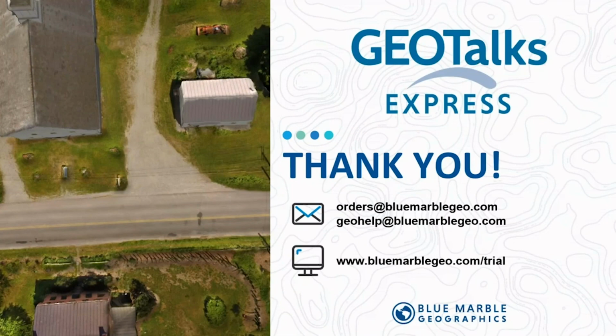Somebody asked very quickly, how do they generate the flight line? It happens automatically. Again, load your drone images into the Pixels to Points tool. I believe it's an option in one of the menus at the top. Mackenzie, I don't know if you can remember. It's from the map menu. You can load images that are in the Pixels to Points tool dialog back into the main view of the Global Mapper workspace, and that will create the flight line. And it does automatically. And beyond that, I just clicked play and it went. You can obviously, again, do the flight line manually as well.